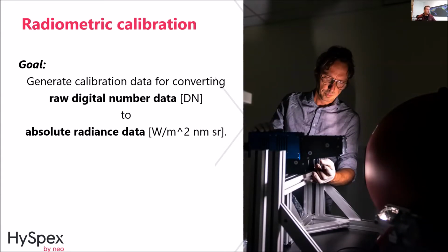When you do a radiometric calibration, it's extremely important that you have a uniform integrating sphere, because all non-uniformities of your sphere will mean non-uniformities in your camera. So typically those integrating spheres are a lot larger, or the port in the front is smaller relative to the size of the sphere. The goal here is to generate a matrix that tells you the response differences of every pixel.